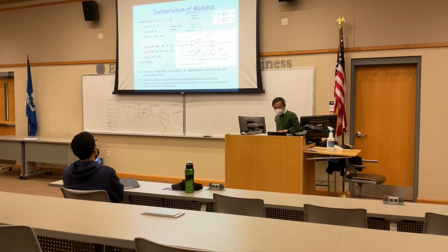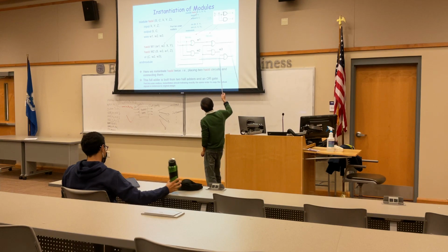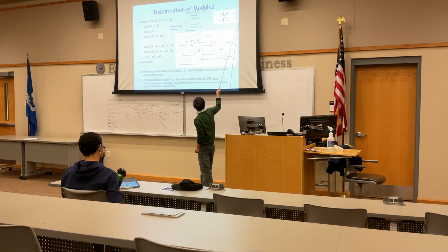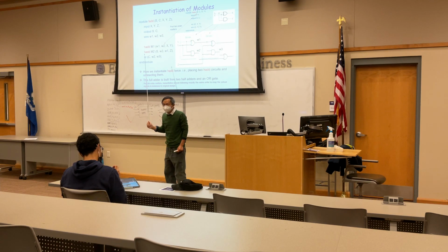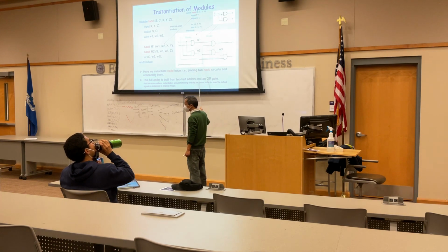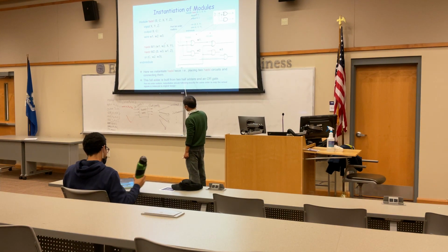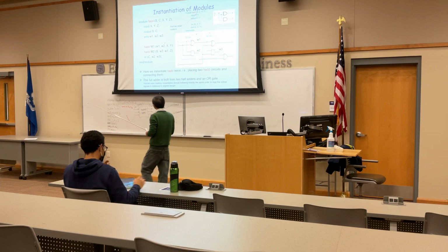Now, instantiation of the module. Once we have already designed this half adder, we can reuse it, call the instance, and then construct a full adder like this. So this way we're going to show you how we can call the instance.